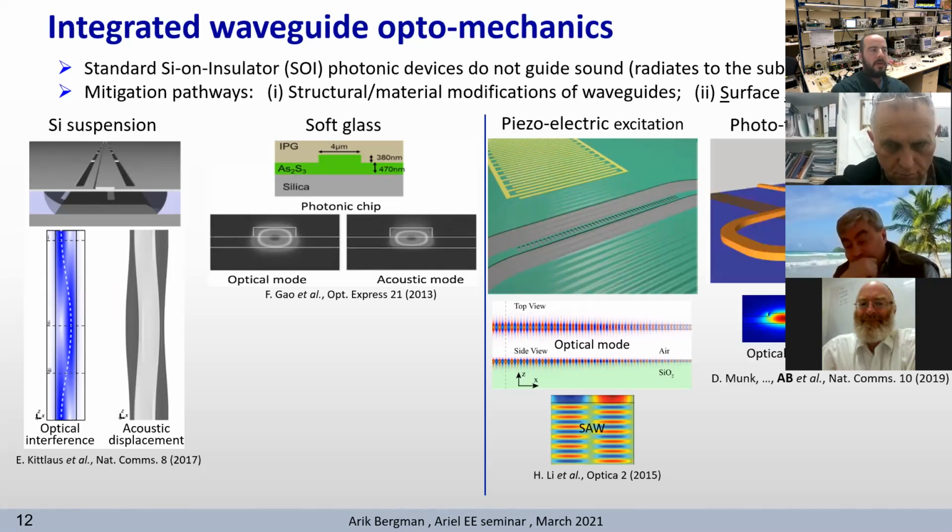We took this principle one step further and showed in a recent publication that surface acoustic waves can also be generated in a standard silicon device layer through absorption of modulated pump light in metallic gratings. The acoustic waves are detected via photoelastic modulation of an optical probe, which propagates in a standard SOI waveguide. The photothermomechanical transduction efficiency is still low relative to piezoelectric actuation, but strategies to increase the efficiency are currently under study.